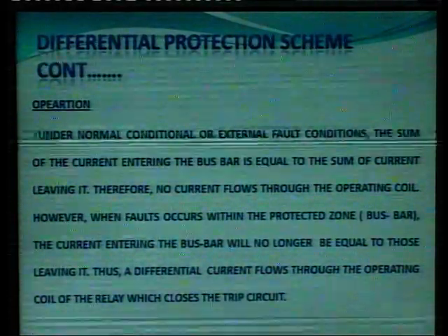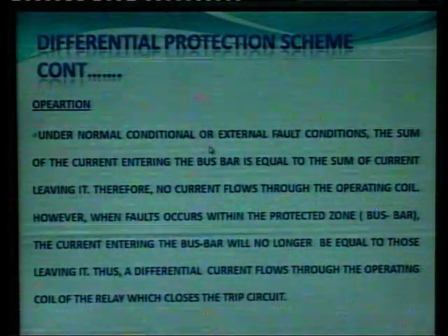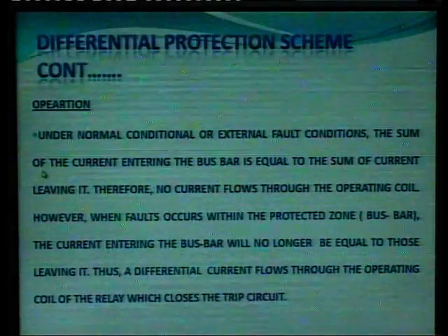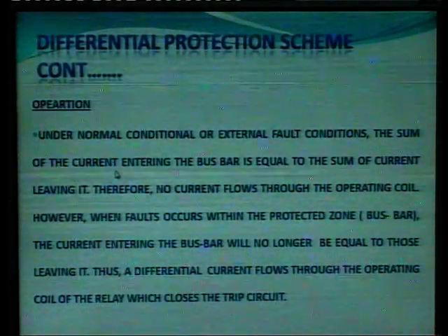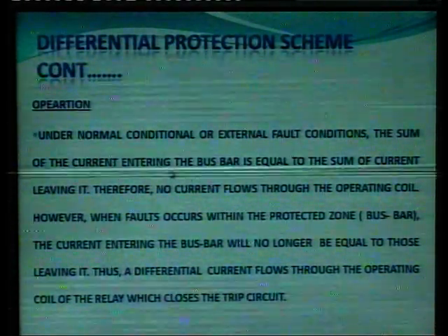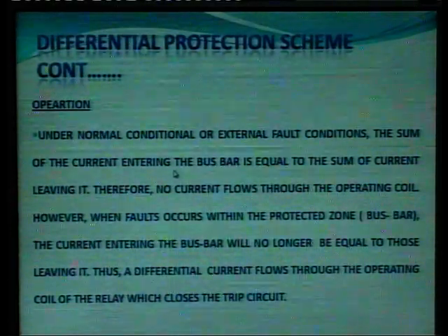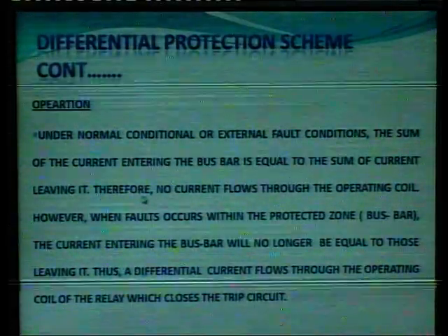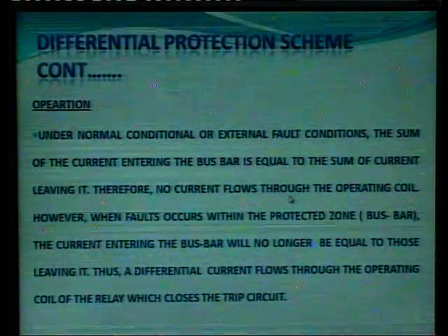So, operation under normal operating condition or external fault condition, the sum of the incoming current must be equal to the sum of the outgoing current, that is KCL, Kirchhoff's current law. Therefore, no current flows through the operating coil.